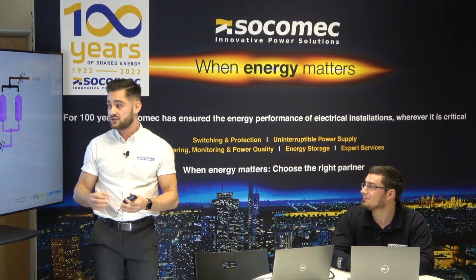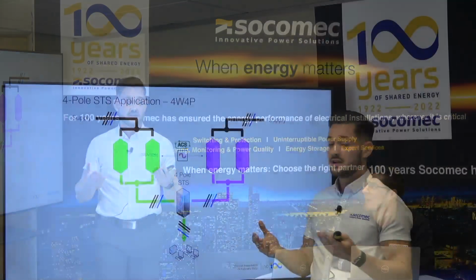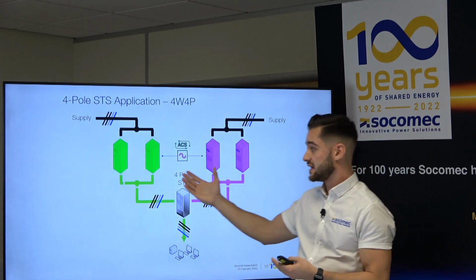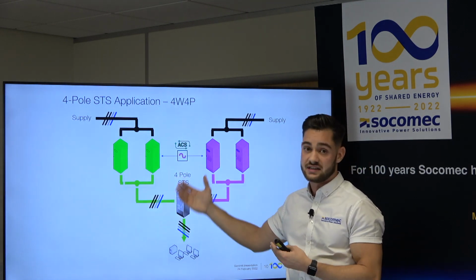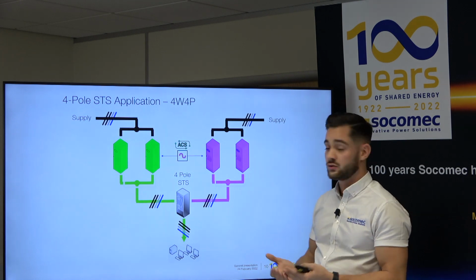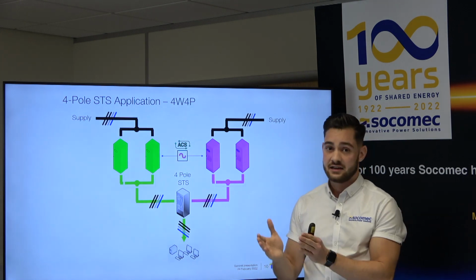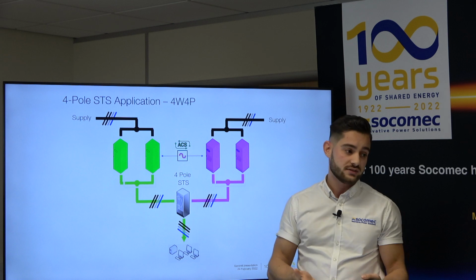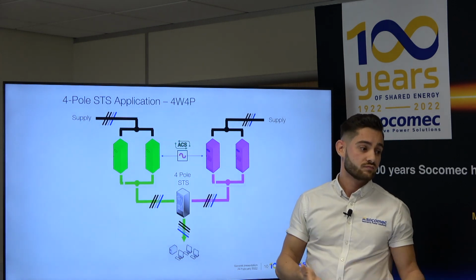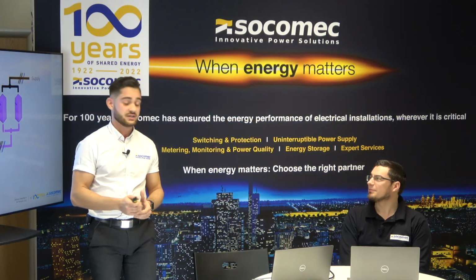Absolutely. Just to put a little comment on this, we can hear sometimes that it's faster with a synchronized source on the input of the STS, but the STS can perform unsynchronized transfer as well. It would be slightly longer, so with, let's say, up to 10 milliseconds with this kind of device. Still well within our 20 milliseconds. So 100%. Yeah. And that's the key point.